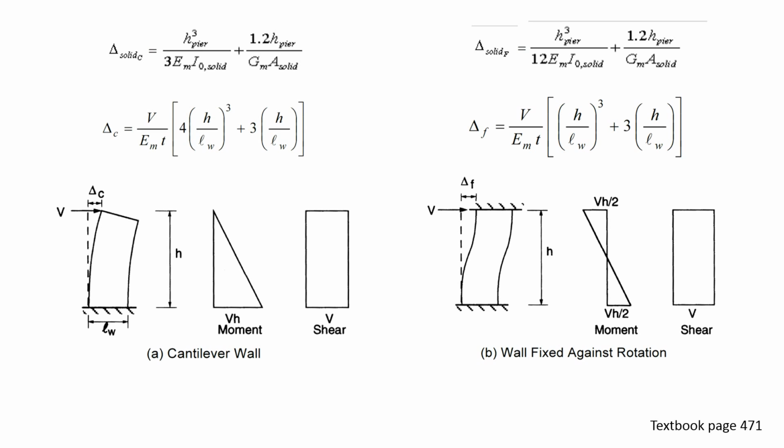So the important thing to remember is that we're not concerned as much with the rigidity itself as much as we're looking at the relative rigidity and comparing the rigidity from one area of masonry to another. So if we're looking at similar reinforcement configurations, in many instances, we're going to have the same relative stiffness, whether or not we're looking at elastic analysis or inelastic analysis. It's just the relative difference that we're more concerned with, and so that's why this analysis is generally okay when we're distributing in-plane loads around openings and movement joints.